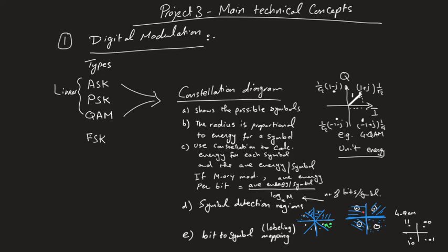There are many ways for doing the mapping. We did not really study the labeling. We did not really study those, so this will basically be given to you in one description or the other. You should be able to put it on a constellation diagram, or figure out, based on the given labeling scheme, which symbol is going to be transmitted from the constellation diagram's possible symbols. Okay, that's also another important feature. Constellation diagrams can also be used to calculate bit error rates, but we did not go through that in this course. You can study that in advanced courses that talk more about digital communication systems.